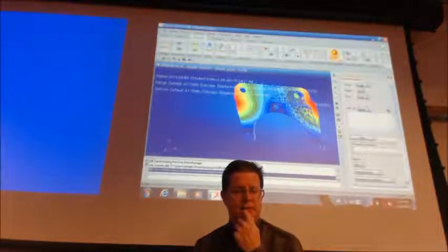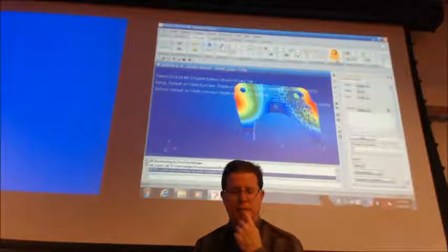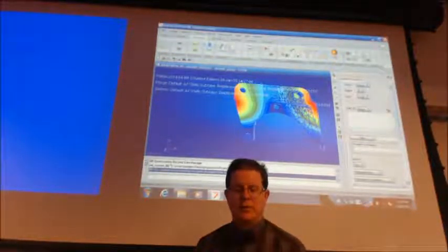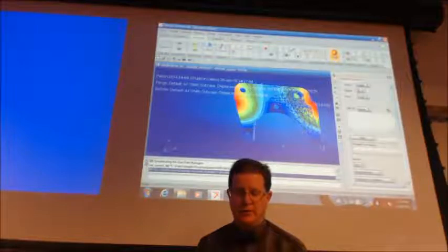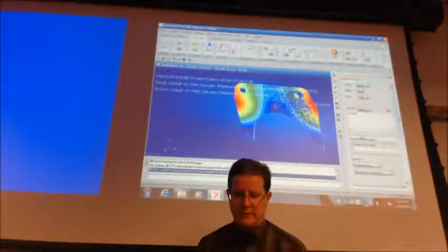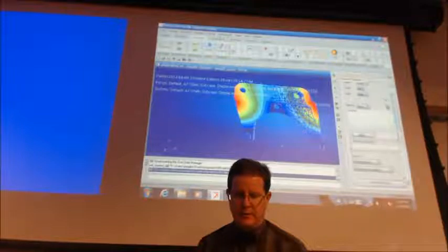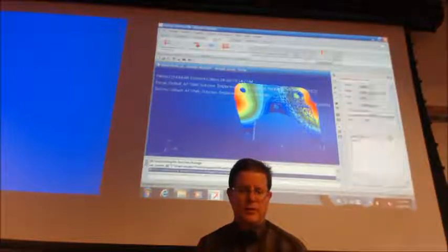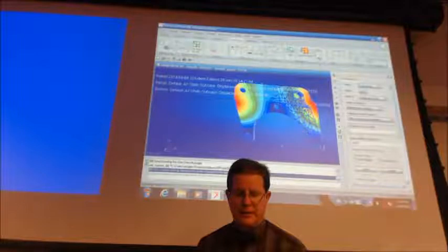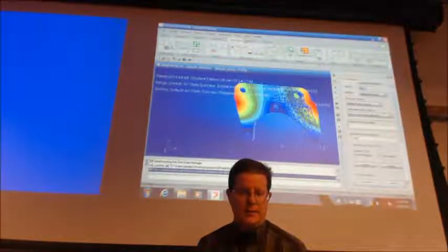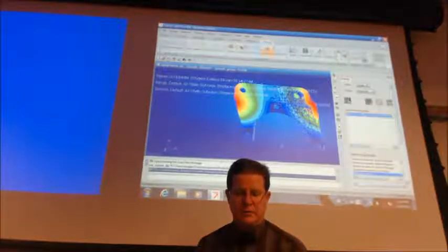On properties, you can do your isotropic properties, but instead of the 1D stuff that we're doing right now, you're just going to go to 3D properties. Then you won't have to pick where your nodes and everything are. No, this will do it for you. When you're meshing, you'll just select this, and it does its thing. And analysis, you run it, and results, and away you go.